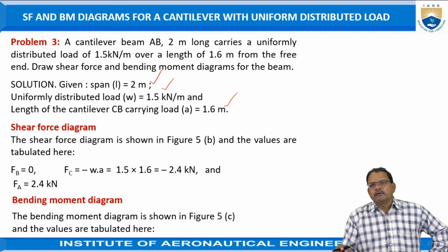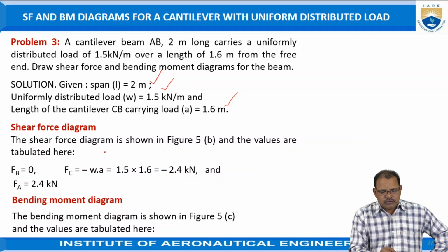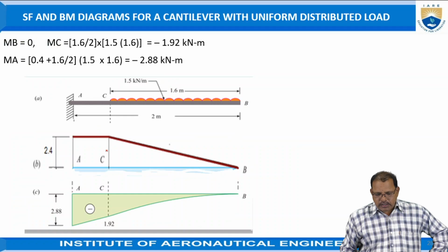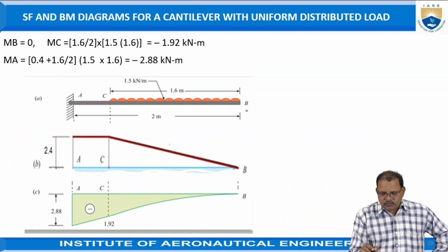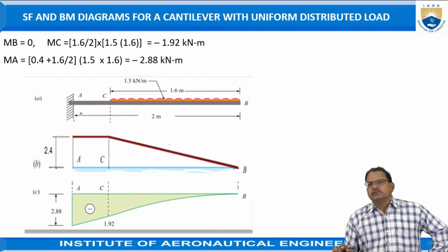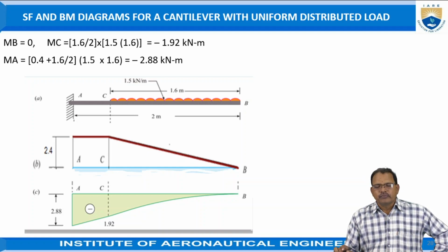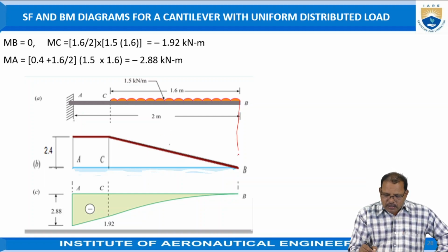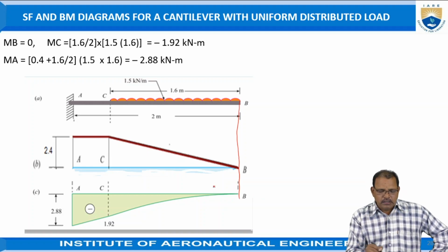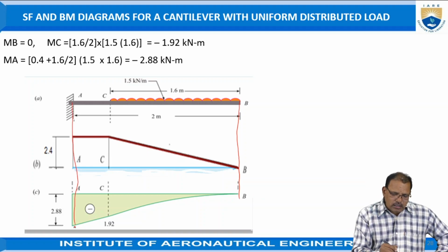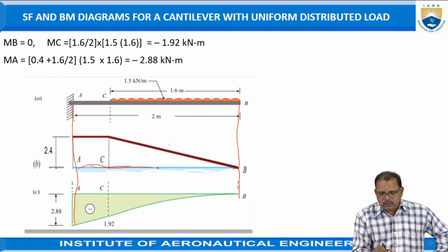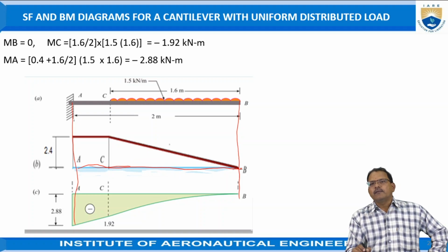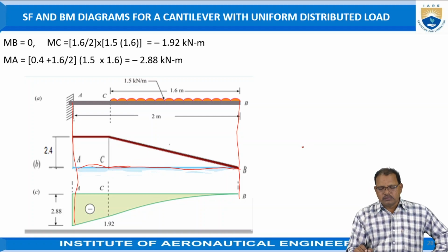Okay, in this one the given data is the shear force represented here now. This is the diagram that is given. Now after representing the forces which are acting on the beam, draw lines which are passing through point B, where this end B is represented. One more is the end A. At a convenient length, draw lines to represent the ordinate or length of the beam for drawing the shear force diagram.